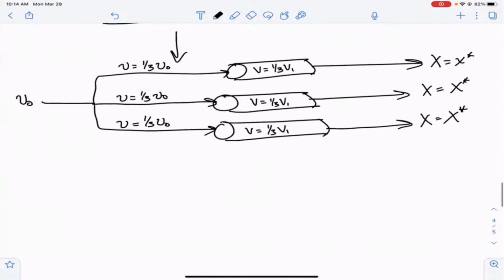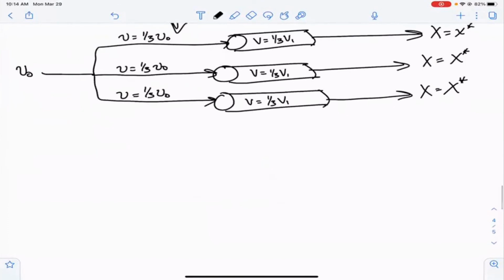So a couple of minutes ago, we derived an expression for how the conversion changes with all these different variables, right? We said that the natural log of 1 over 1 minus the conversion was equal to Kc times AC over the linear velocity times the length, okay?